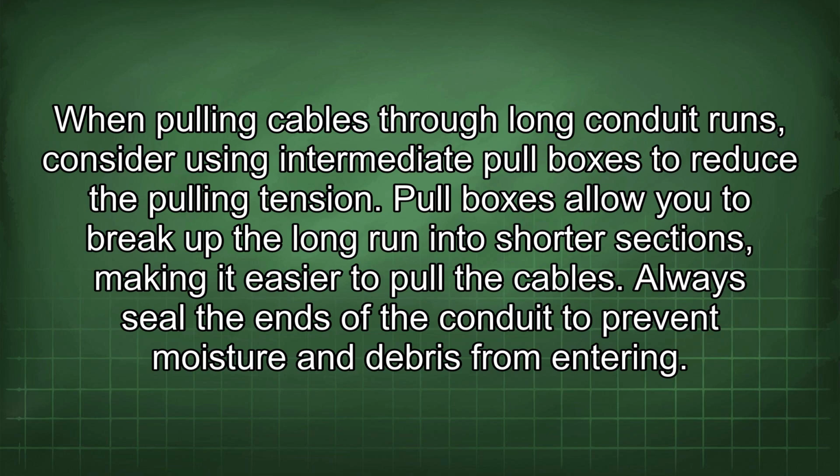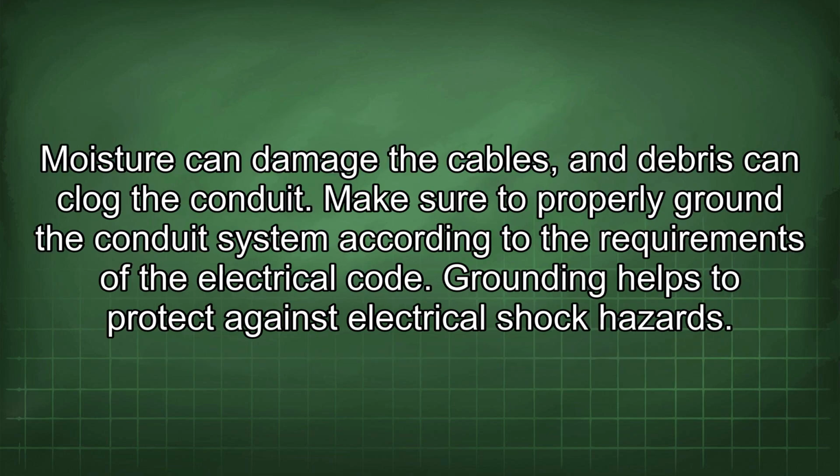Always seal the ends of the conduit to prevent moisture and debris from entering. Moisture can damage the cables and debris can clog the conduit. Make sure to properly ground the conduit system according to the requirements of the electrical code. Grounding helps to protect against electrical shock hazards.